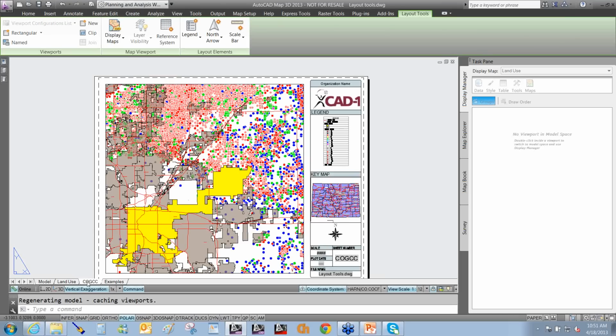Now, do display maps work in Civil 3D? Yes, they do. The thing that you've got to remember is that when bringing in GIS data, you've got to really watch out what you're doing about coordinate systems and this whole grid-to-ground thing. When you bring information in, if you don't change it, it's going to come in a planar coordinate system. We don't design off of planar coordinate systems at grid. We design off of ground. So you've just got to be careful with the scaling, etc.